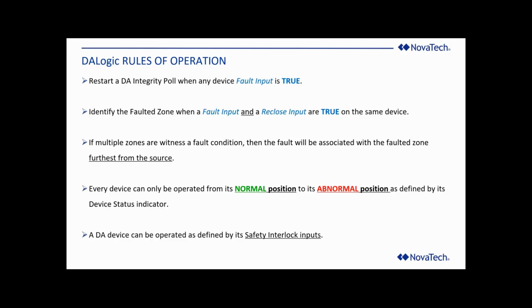It is not going to switch a device and then re-switch the device unless it is specifically coded to do that. And so that prevents the DA system from what I call chasing its tail, so that you don't have one DA event that switches to completion and then it is affected and undone by a second event.